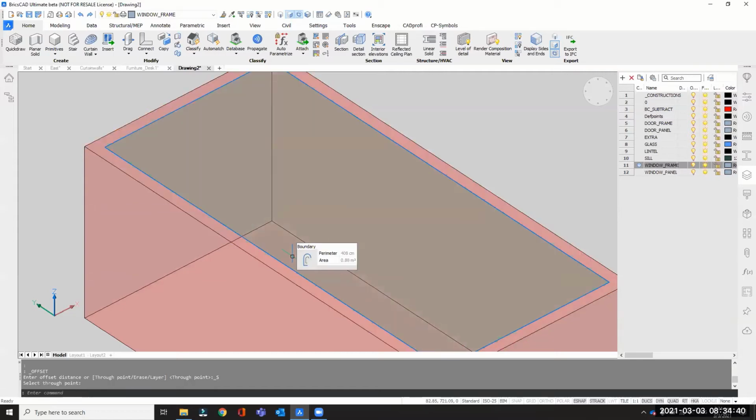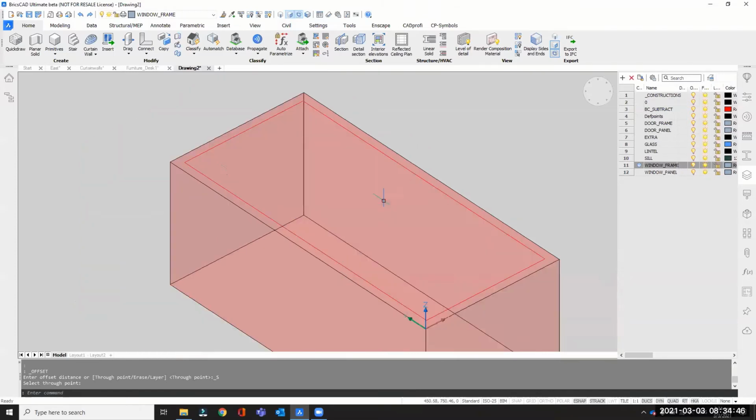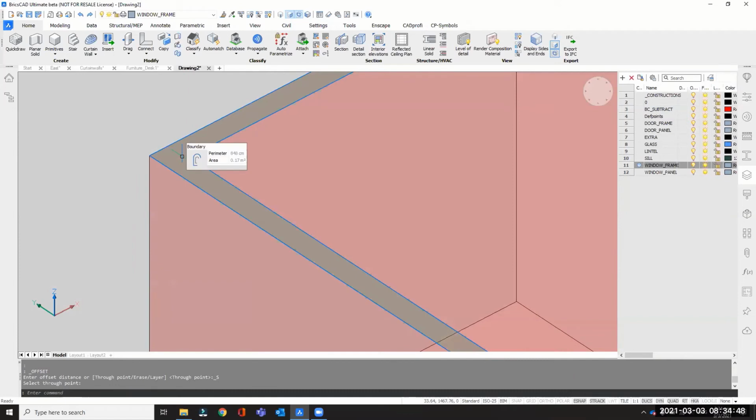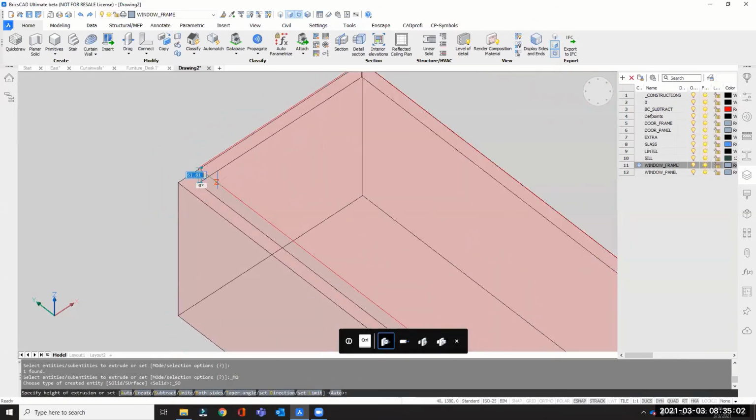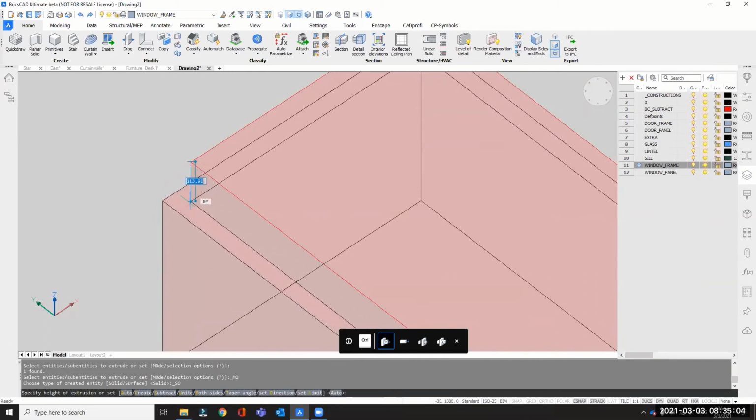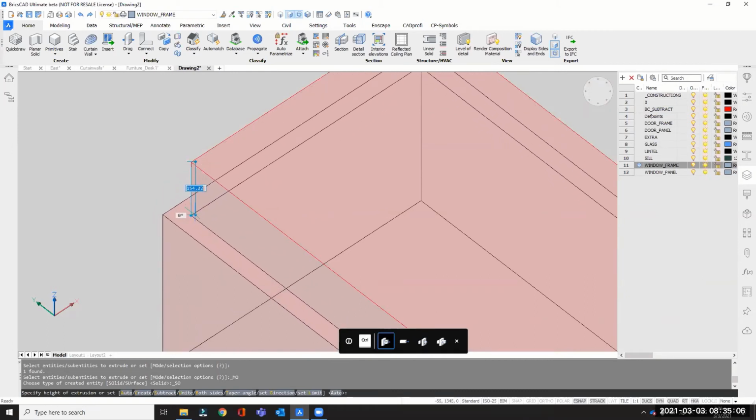And click enter. Since we have our boundary selection on, it's selecting the boundary of this specific enclosure for us. And what we want to do is actually the frame, right? So let's go to the outer boundary and go into our quad, and you'll find the solid extrude that's already there. So let's extrude this, and you would find that when you extrude, it's actually subtracting parts of your solid, but that's not what we want to happen.